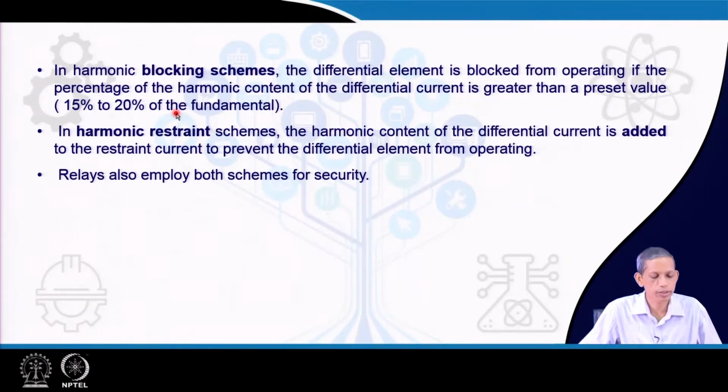This feature is observed from numerous inrush situations as compared to the internal fault. Note that the differential relay should operate only for an internal fault between the two CTs for the transformer protection. But this is an inrush situation, not an internal fault at all, so it should not operate in that situation.